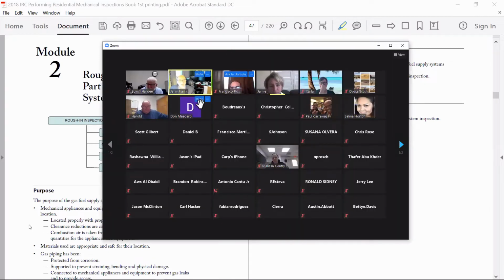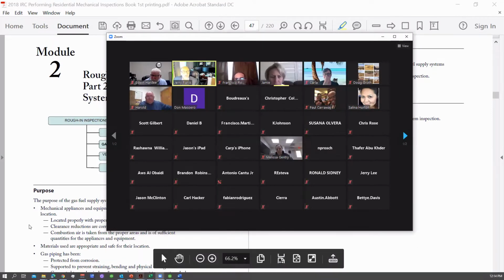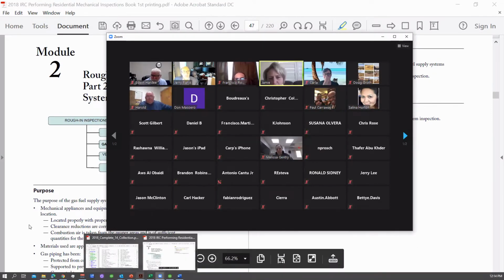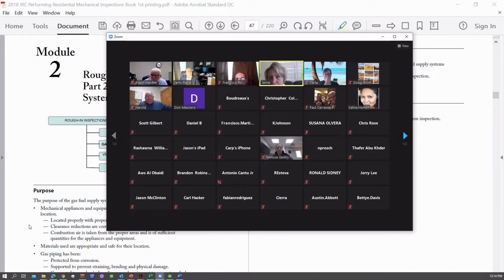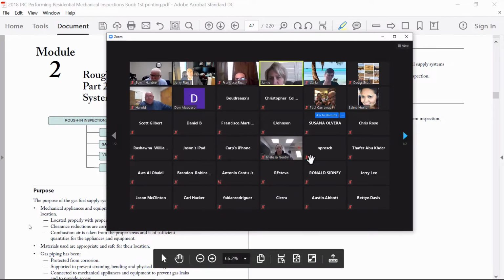And what type of construction documents do you receive in your building department for fuel gas piping systems? So we'll get a single line drawing to make sure that they're installing the right size pipe. Depending on what the item is, sometimes we ask for manufacturer's installation instructions because technology is ever changing, and we want to make sure the customer is installing it per the manufacturer's installation instructions as well. Title 24 documentation maybe for the energy code.